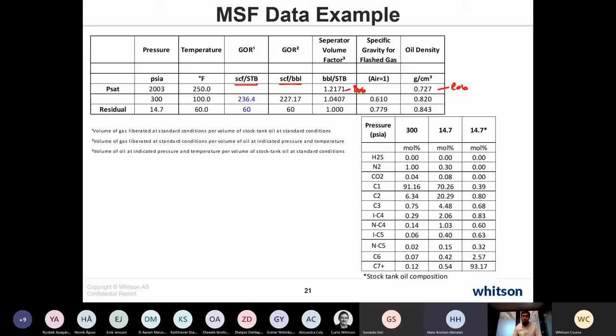If you are using a CME, for example, I just put on the mixer, and if I wait 10 to 15 minutes to get equilibrium, then it's sufficient for each stage, because I have done experiments where if I wait 50 minutes or 1 hour, it's approximately the same.